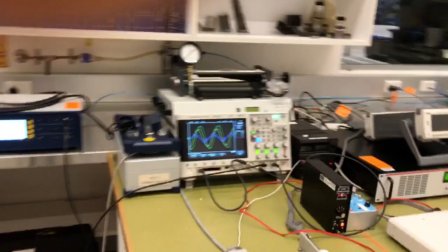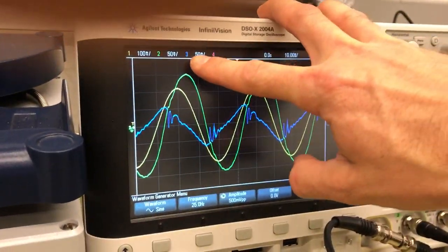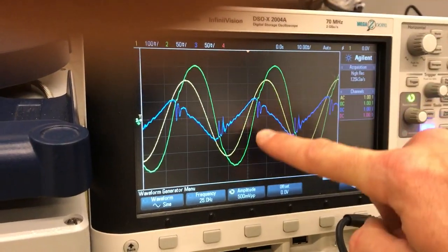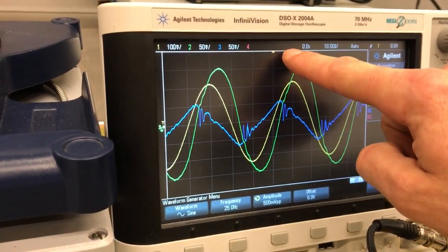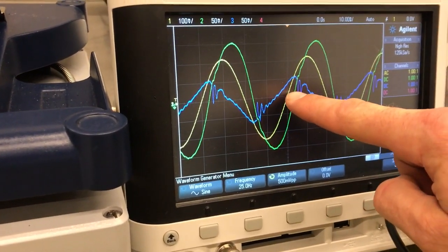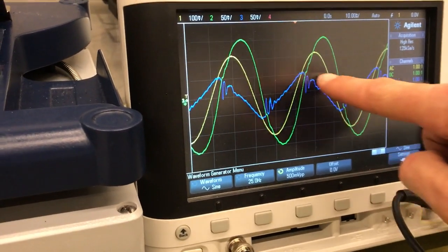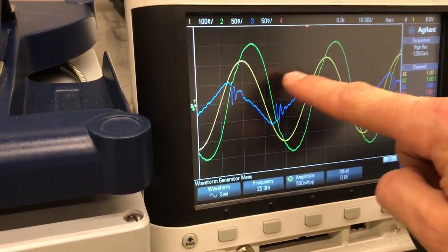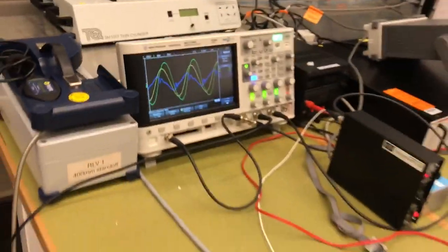And if we go back to the oscilloscope, you can see that my channel is being set up to have 50 millivolts per division, and these are the divisions on the oscilloscope: 1, 2, 3, 4. I have 8 divisions in total across here. Clearly it's a vibration, so this is plus minus 50 millivolts or 50 millivolts peak, and so one division at 50 millivolts per division gives me my acceleration level that I'm interested in.